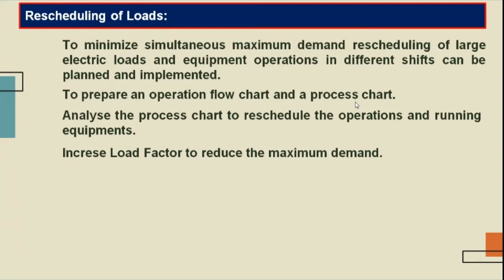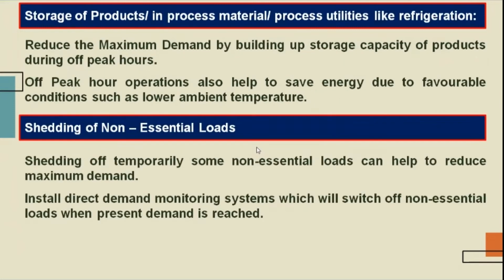Based on that, I can think of in which part of the day which load should be utilized, so that there will be optimization of the maximum demand. Then analyze the process chart to reschedule the operations and running equipments. Similarly, increase the load factor to reduce the maximum demand. So these are some of the points related to the rescheduling of loads.